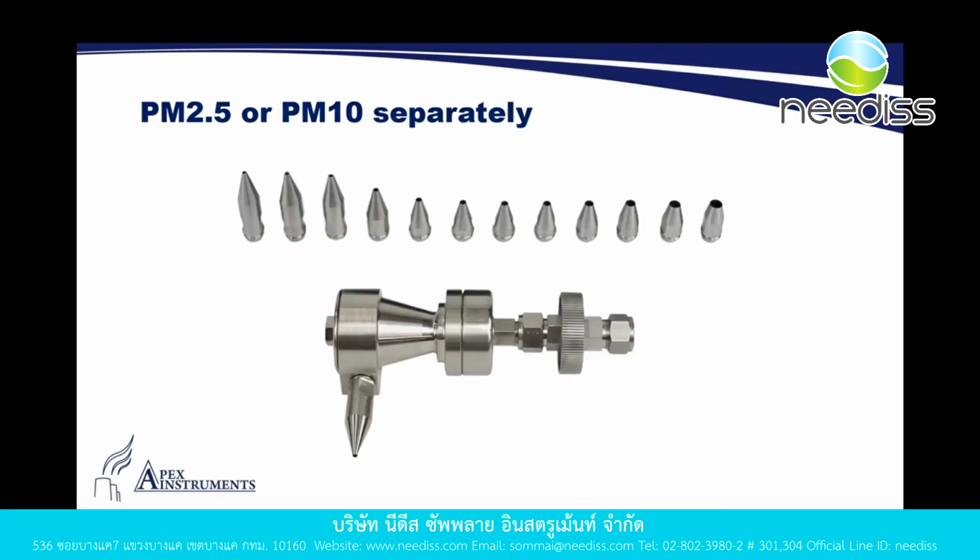This is a quick look at what I was just talking about in terms of an individual cyclone, the PM2.5 or the PM10 cyclone done separately, not together. So it's basically the exact same design. We've just removed the button hook nozzle, the little leeway that connects both of those cyclones in series, and we go directly from either the PM10 or 2.5 cyclone here to our filter.